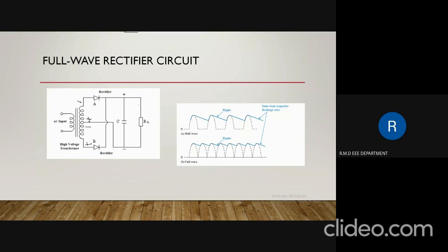During this half cycle, you can observe that the current flows in the same direction as in the positive half cycle of the supply voltage. In this way, we get an output voltage waveform in a rectified manner, the same as the sinusoidal voltage waveform. Here, this blue line represents the voltage waveform with the capacitor. With the help of the capacitor, the pulsation of the output voltage is reduced.